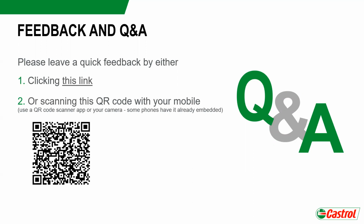Thank you. So Optigear synthetic PD-ES is a synthetic group 4, which is a polyalpha olefin type oil with the plastic deformation additives in it. Optigear 800 is a PAG, which is polyalkylene glycol. So they are different types of technology of lubricant. Now the 1500 there is the viscosity at 40 degrees. So this is a very high viscosity polyglycol product that's being used for the bearings of the rollers in the coal grinding application.